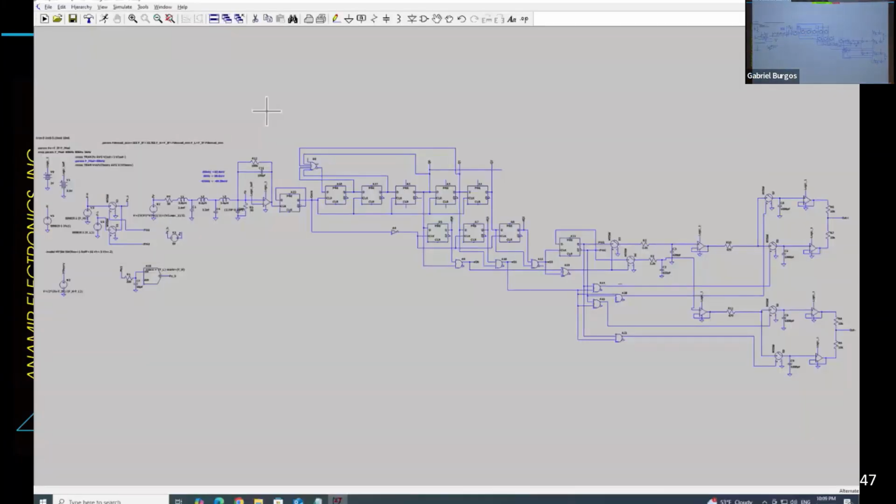This is my LTSpice simulation of it. You've got a digital logic circuit here, which is concerned with just operating some analog switches to sample signals at the right time. Basically, it's about averaging and determining how long the circuit sits in each state. The analog part of this is just an averaging circuit, just a low pass filter. The digital part amplifies the difference in frequency between two points.